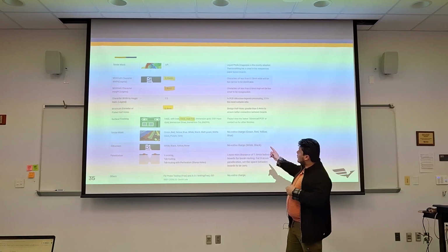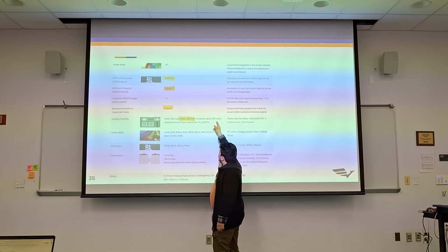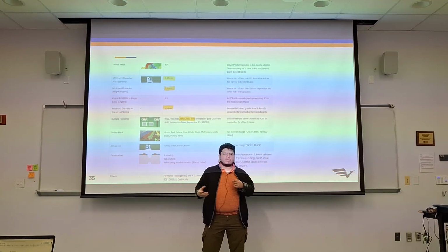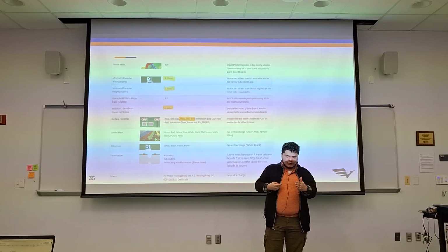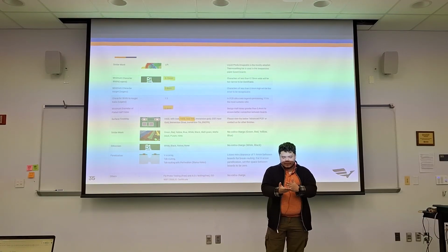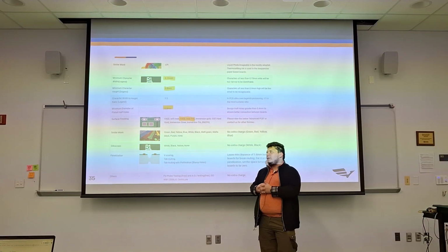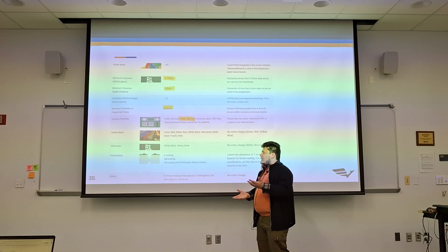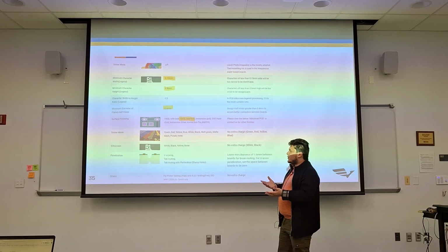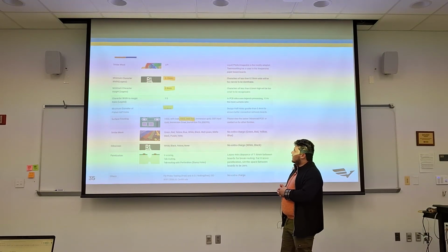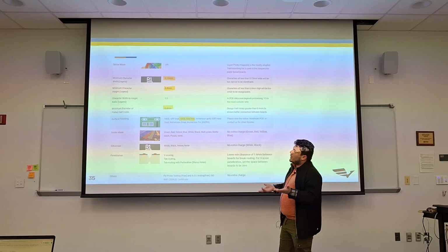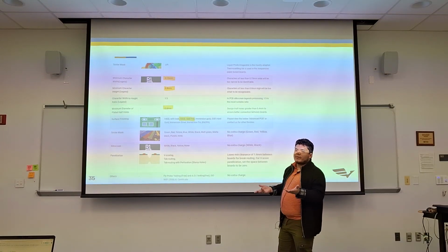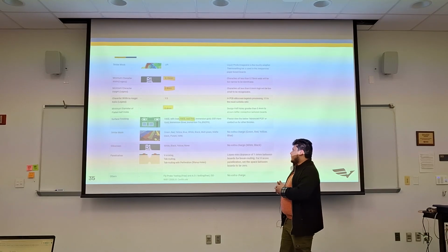And then hard gold, this is what I'm talking about with the edge connectors, because you need a harder material if you're going to be slotting in or removing. There is a cost trade that you could do. If you're not connecting them all that often, then maybe you don't need hard gold, because it is more expensive, right? Because it's more gold, more processing.